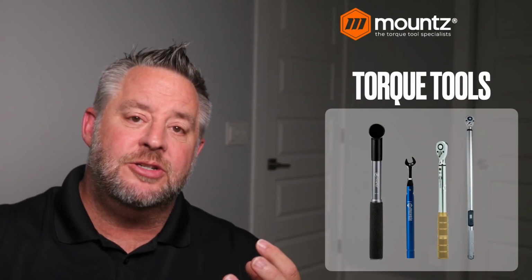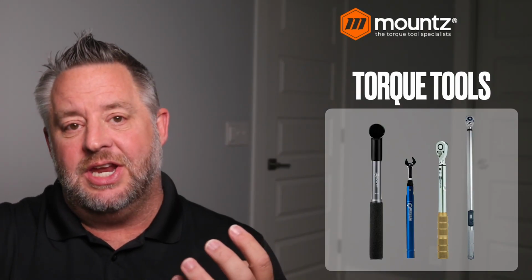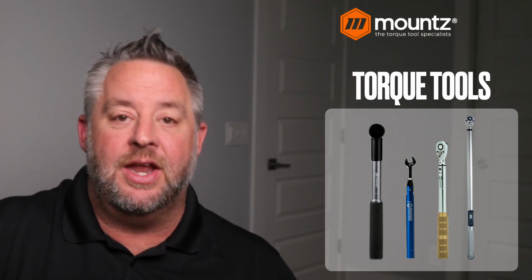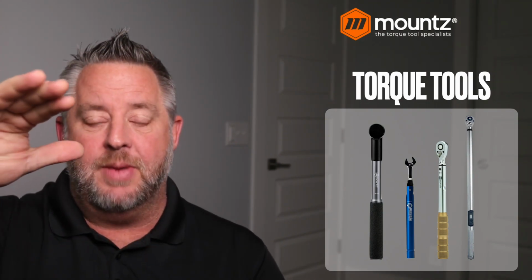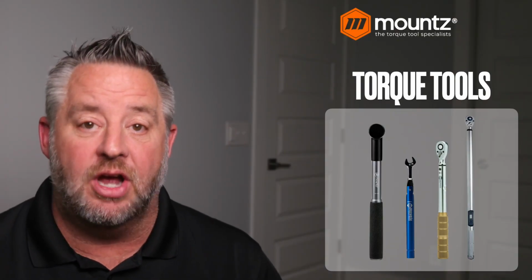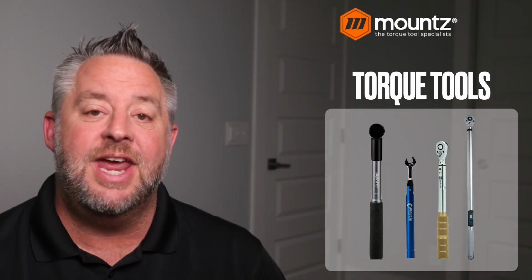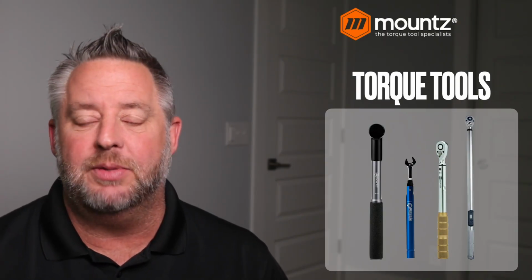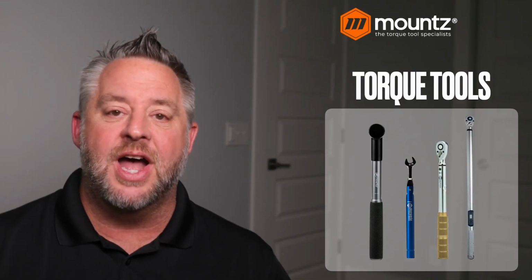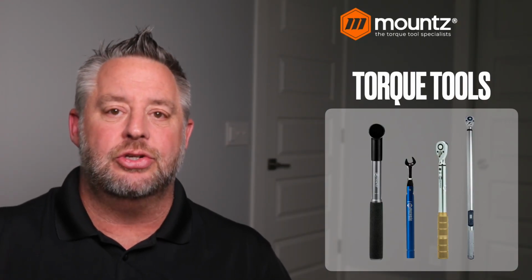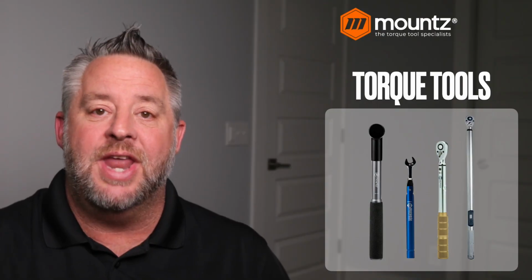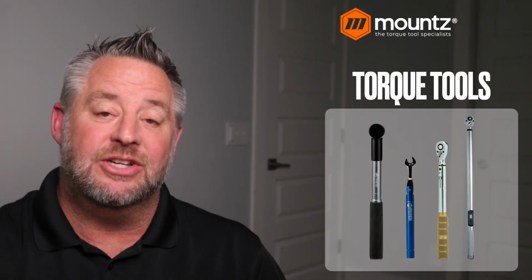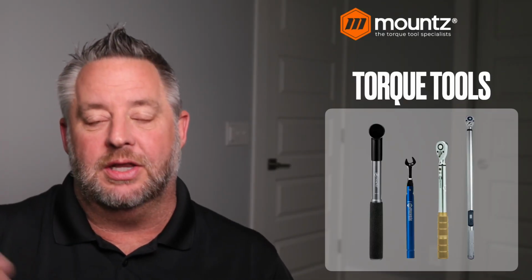There's a cam mechanism in there, and as the tool is being used, that cam will slip, and then we know we've hit a certain amount of torque, and the tool will reset itself. And so that is a cam over style wrench. This is a really good wrench to use in highly critical torque applications because it does not allow any additional over torque when that wrench is being used, because it can only provide as much torque as the cam would allow.